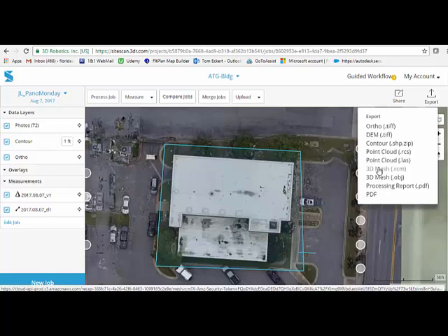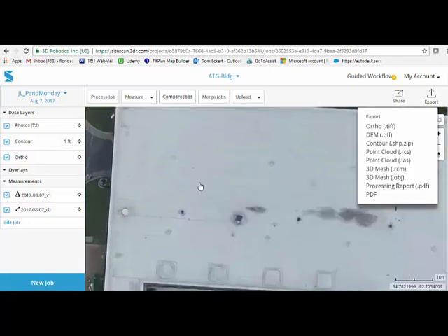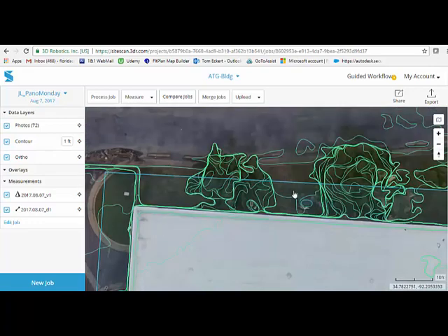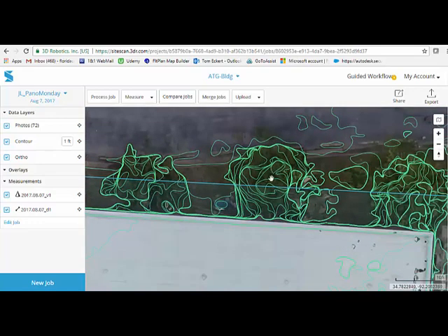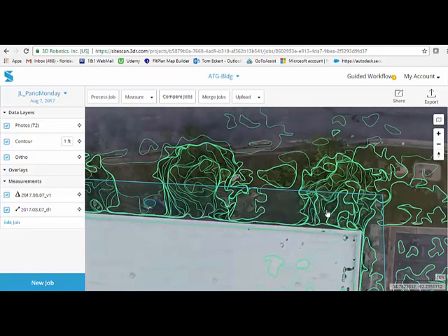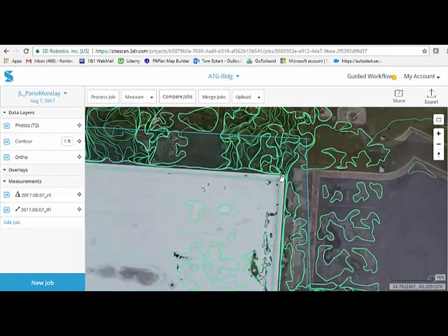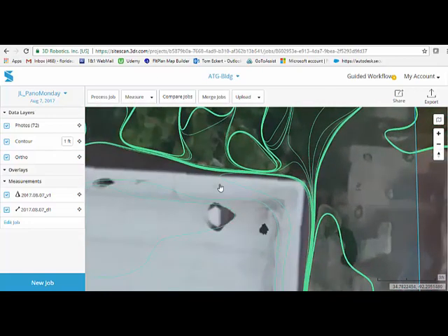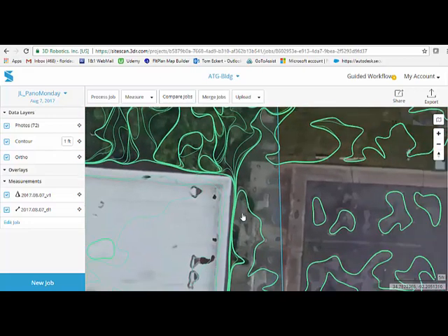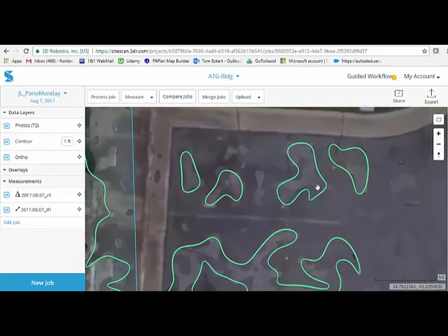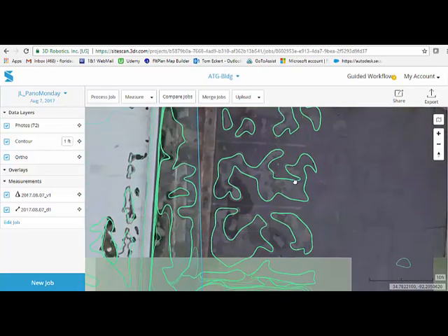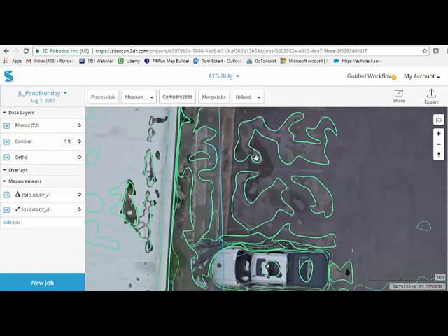So we want to avoid you using those to create your contours, or worse, just taking the contours themselves from the site itself, like right here, and using these contours, which is a tree, by the way. You can kick out a PDF of the contours. You can realize that the contours go up here, and you can't count the number of contours that it takes to get up to your 32 foot on the top of the building. But you can see that contour was created from a water spot on the asphalt. And so that may actually be the elevation, but I tell you one thing, it surely isn't a grade break, and that spot on the parking is the same as this spot as far as elevation goes.